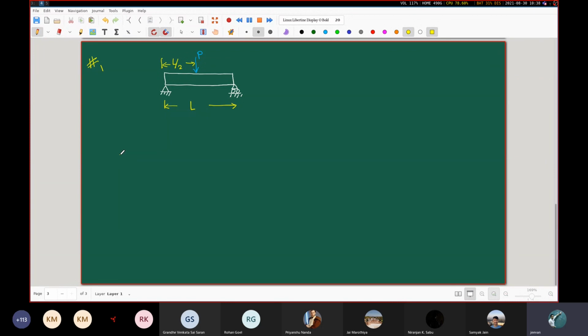When we say shear force and bending moment diagrams, what is the diagram about? The diagram is basically a plot of the shear force as we move from the left to the right of the beam. What we basically mean is that you take different cross sections here, here, here, here, and here. As you move along the length of the beam from the left to the right, taking different such cross sections, what will be the values of the shear force at different cross sections?